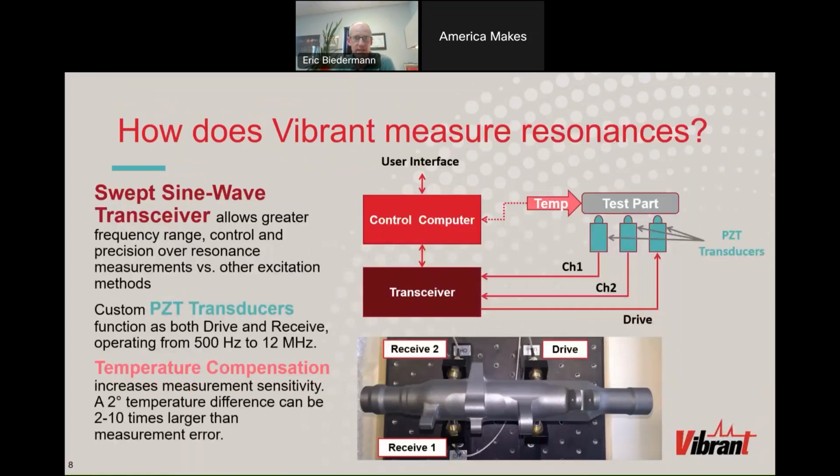The equipment is really all about getting a set of piezoelectric transducers in contact with the part to run the resonance scan. Our scan comprises a swept sine wave excitation. So we begin exciting the part through this drive transducer, and we continuously increase the frequency of the excitation. And anytime we hit a natural mode of vibration, we see a spike in the amplitude of our signal, and that's the resonance mode that we record into our database.